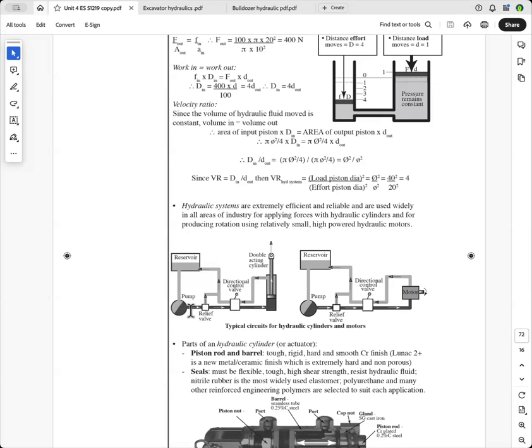Sorry, this is the motor here, but the motor is very similar to the pump. So this is just driving the hydraulic cylinders here. There's the levers that operate the valves to allow the hydraulic fluid to go in. This is called a double acting hydraulic cylinder. So when you want the ram to go out, the hydraulic fluid goes in there and then it goes out there.